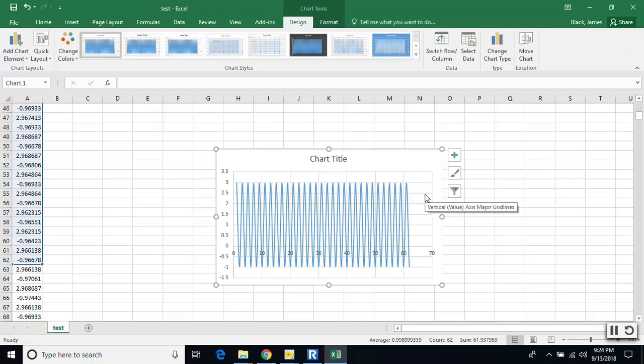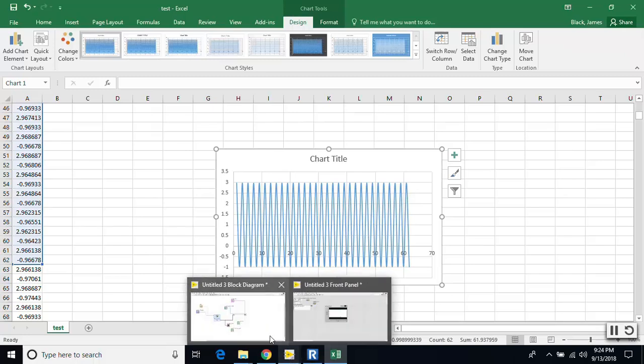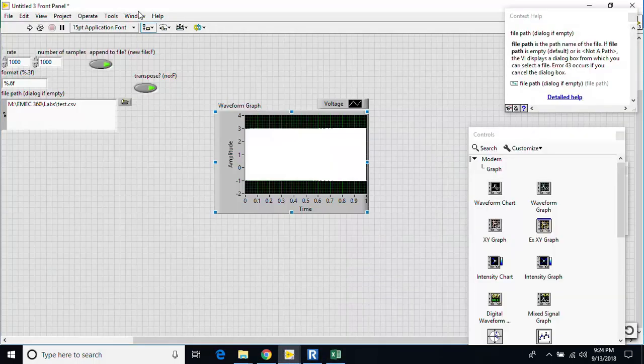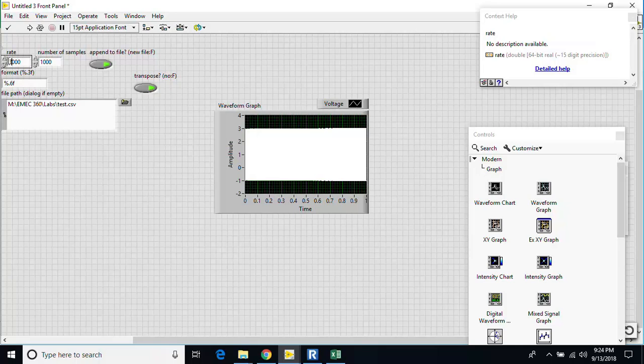Once you do a test like this, at this point you would want to adjust your sampling rate and the number of samples taken so that you are satisfying the Nyquist theorem and the requirements of the handout. And once you adjusted everything to what it should be, let's say you needed to adjust this up to 3,000.